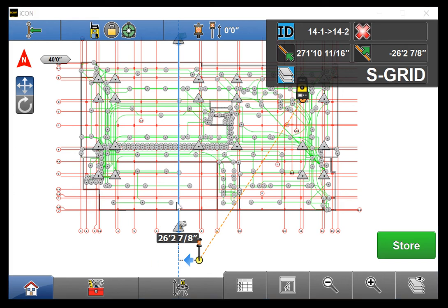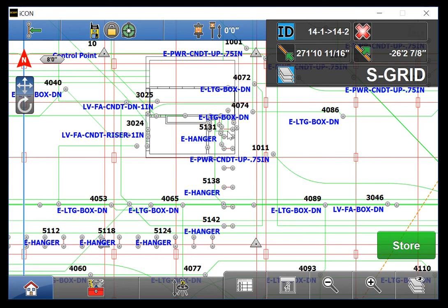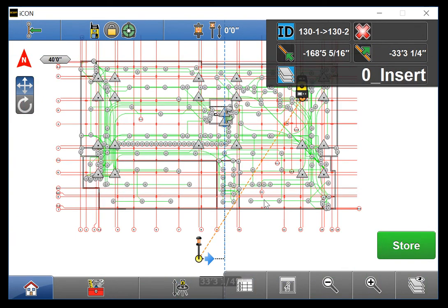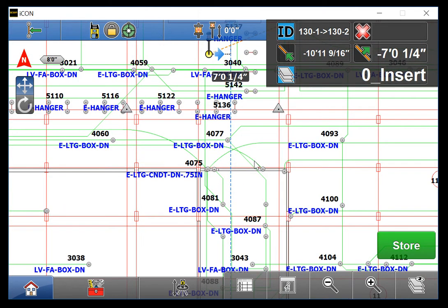Typically, when working with long straight lines such as this control line, stations don't matter anyways. But when working with shorter lines, especially defining a room or a column, I use the green flag and the negative values to know when I've gone too far past the line.